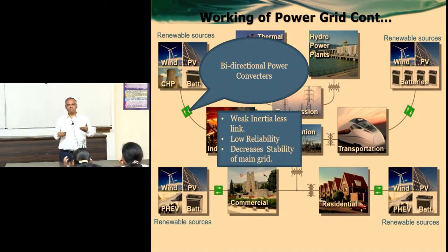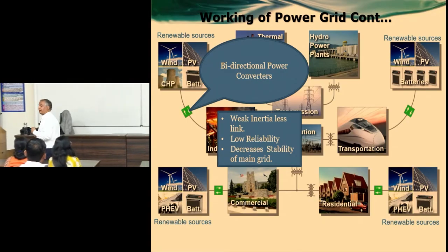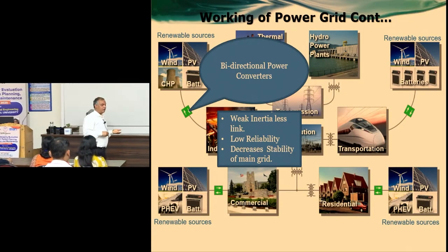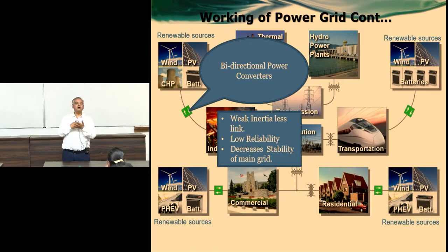You can defer your washing schedule, you can defer your air conditioner also sometimes, because electricity for essential service may be required, and then accordingly you can design your priorities also. So load priority can also be defined based on your requirement. A load deferral algorithm can be designed based on your energy requirement. So smart devices are there which are continuously having access to your energy consumption pattern. They have access to the energy stored inside the system, and the real-time power being generated. Depending on them, they have some optimal algorithm through which they are continuously switching on or switching off your load.